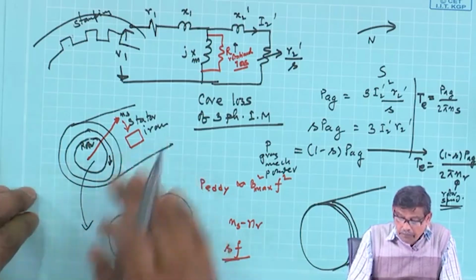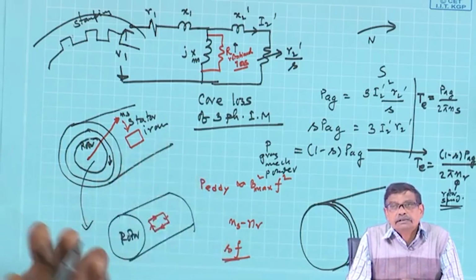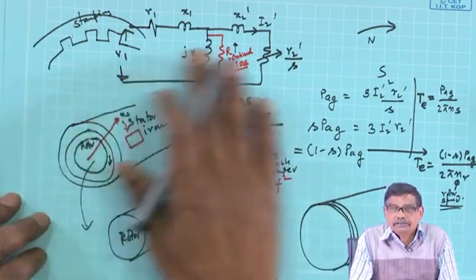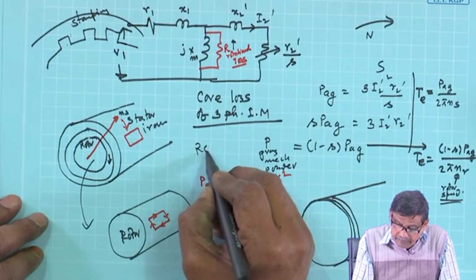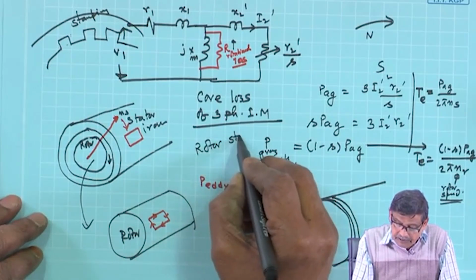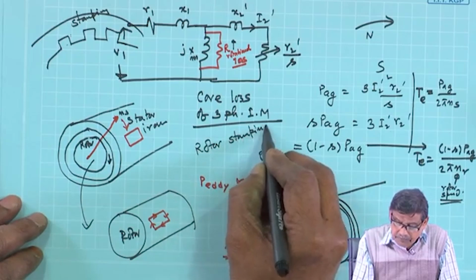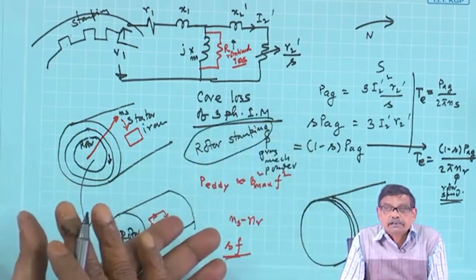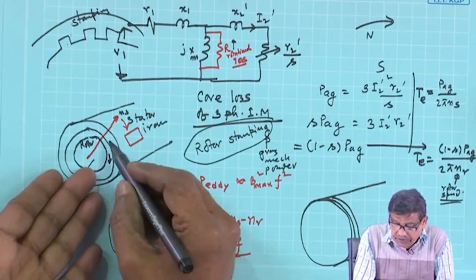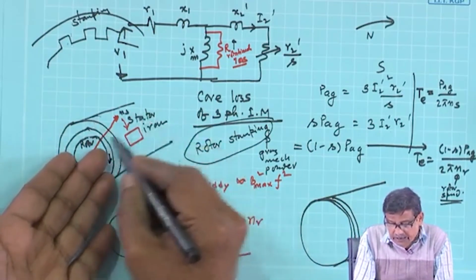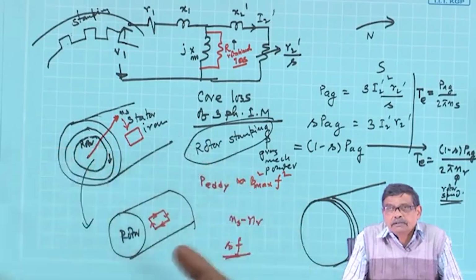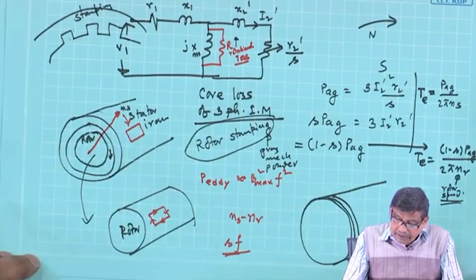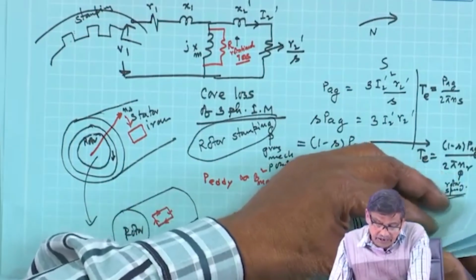So, always remember circular, thin, slotted plates are used. Next class I will show you a rotor stamping. A number of stampings are insulated from each other electrically. If you do not insulate them from each other, then the eddy current path will remain, they will short circuit. So, that is the thing, we will use that.